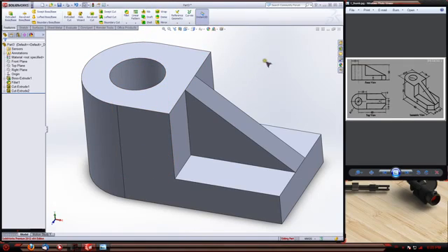I don't know if there's any way you could have done that in any fewer possible moves. Oh, actually, I'm sorry, we're not done. I just noticed some chamfers. If you see here, it's telling us that these chamfers are 9 by 9, so we know that they're at a 45-degree angle because of that.